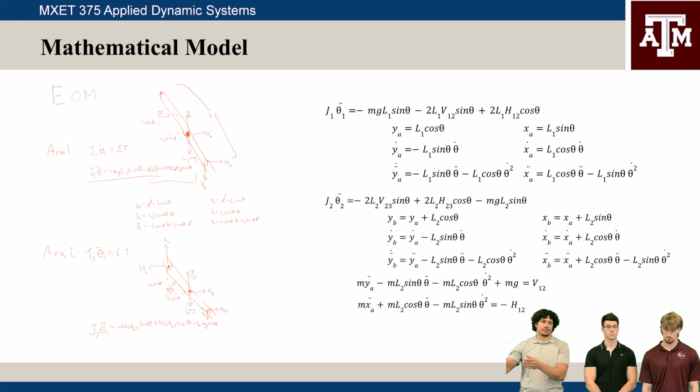We also put the reaction force of the second pendulum arm reacting on the bottom into the equation and accounted for that. On the second, we accounted for the reverse forces from the first back onto the second, went into the middle moment of inertia of the second arm, and then accounted for the third arm's forces onto the second arm.